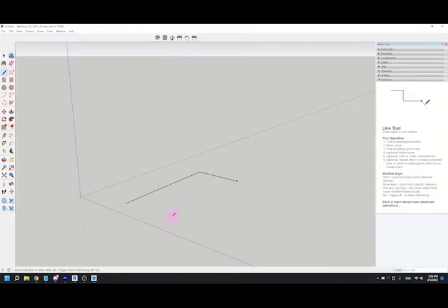So as I'm just putting these lines down and I'm not doing anything at any particular size, we'll notice too that when I get my cursor near where it would meet up with that, it's giving me just some information to say, hey, if you were looking to make a nice parallel box, all of those points would meet. And then it fills in to let me know that this is a closed surface at this point. So that means this is something that I can then make a 3D model out of.